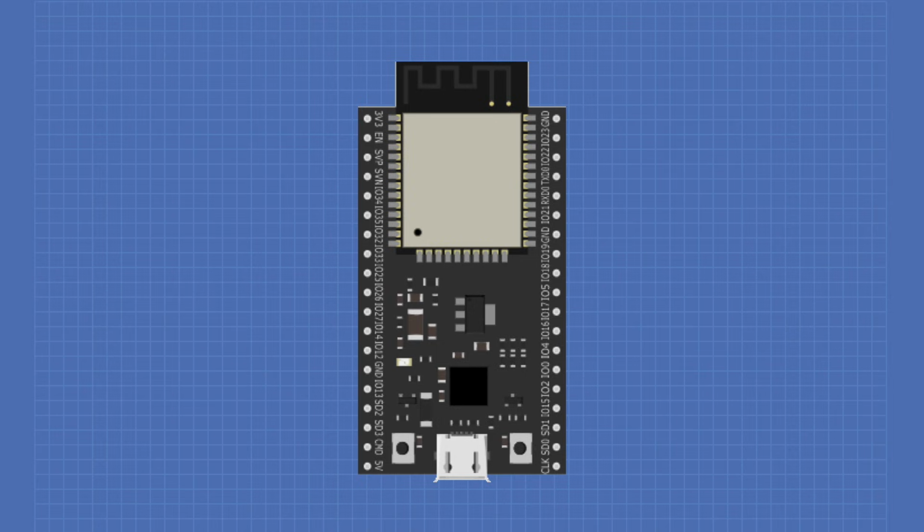Now, you do not have to use the identical module that I am doing, but please note that the pinouts will be different on your module if this is the case, and go by the I/O connection numbers that I'm using, not the actual pins on my module when you're hooking yours up. You'll also, of course, need a servo motor. I'm using a small SG90 servo, but really any servo motor will suffice.